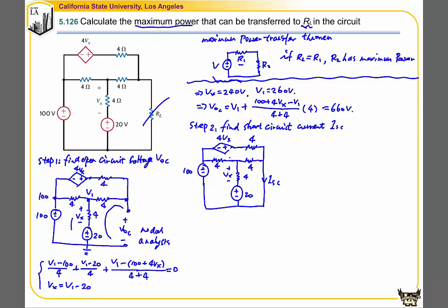Since we already reviewed nodal analysis in the first part in step 1, and we also did nodal analysis in class, in this video we are going to use loop analysis to solve this problem. To use loop analysis, we first need to define the mesh currents. Let's define the mesh currents like what I have here. I1, this is my current I2, and this will be my mesh current I3. I have my 3 mesh currents.